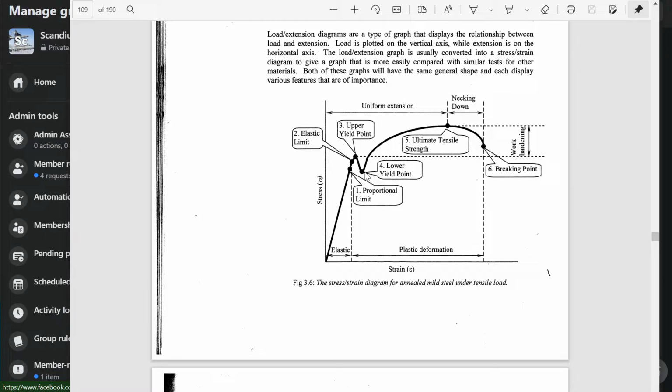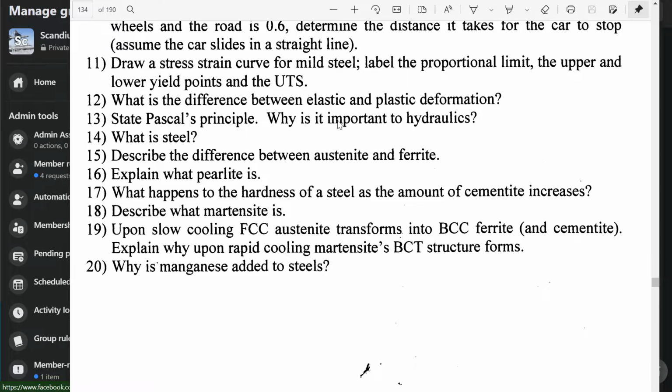And when you buy a material, for steel, I just always use 300. I'm pretty sure that was always the standard for the mild steel we used. I can't remember ever using anything else for structural steel. For reinforcing concrete, we used 450. I'm pretty sure that was set more by the code rather than by suppliers, but I know they did update it to 450 in my time at uni. I'm now 10 years out of the game, so it's possible that's changed, but it's sometimes useful to have some sort of point of reference.